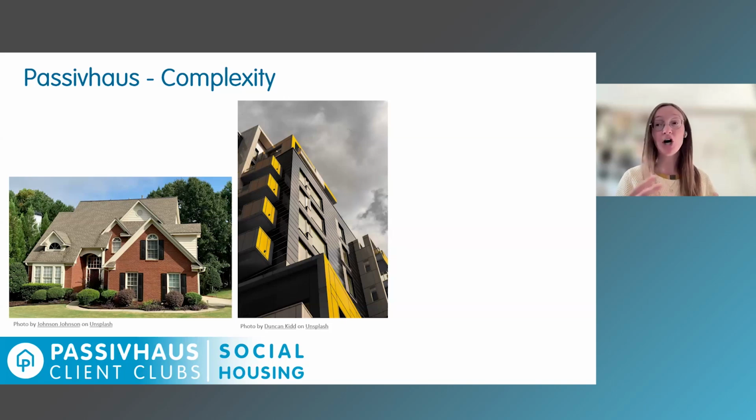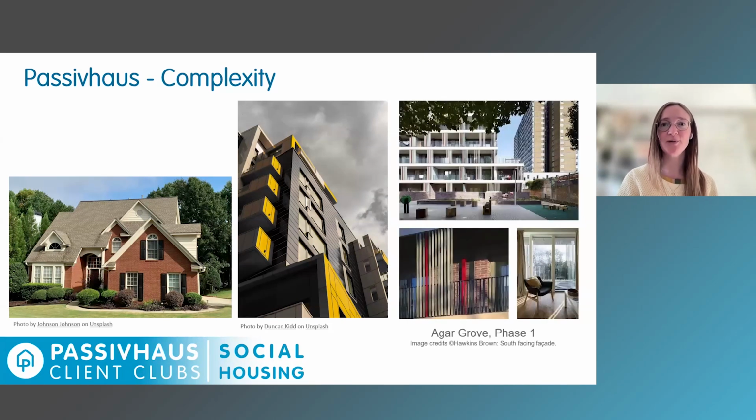And there's other things which are maybe even harder to see from a client perspective when it comes to complexity. So things like the position of the MVHR unit. If we get that right, the installation and quality of the installation can be very easy to deliver in practice. If the MVHR unit is in a suboptimal position in the middle of the plan or something, we've got a long way to insulate ducts, to work out ceiling hanging joist, the duct. Totally lost the word, but anyway, the duct supports that we would need, all of that adds to the complexity of the project, and not just the efficiency of the MVHR, but actually the success of the project from a quality point of view as well.